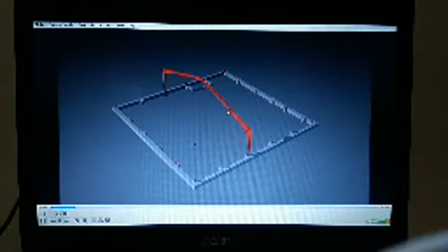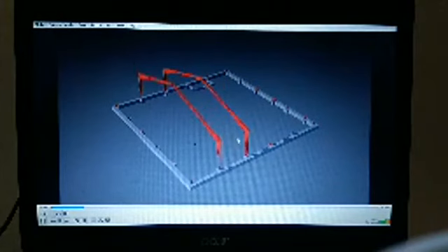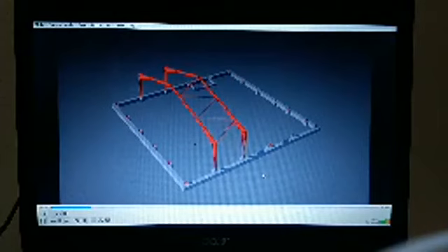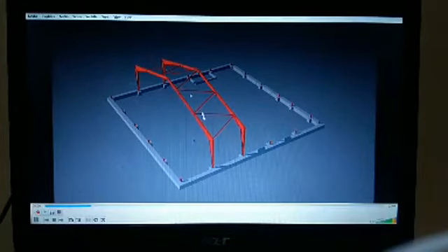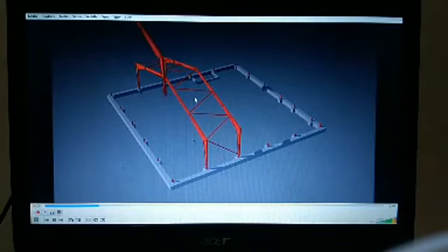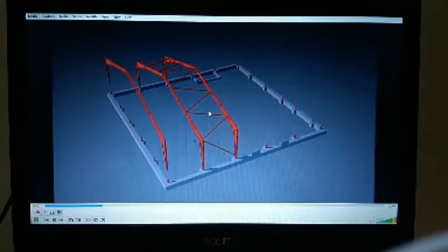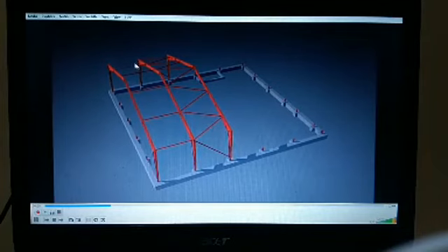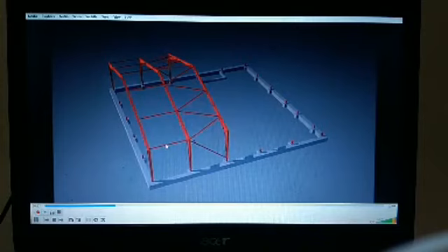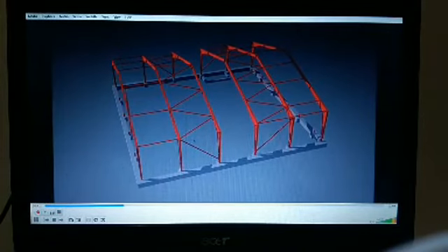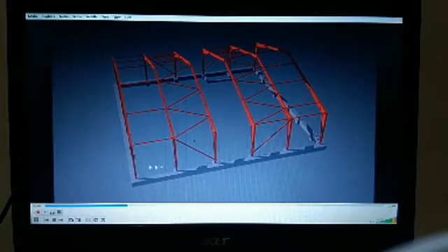Here the video you are observing is a PEB. It is an unbraced frame structure, which can also be called a portal frame structure. This is a bracing on the top of the roof truss, which we call a lateral bracing. These are the purlins, which are supporting the top chords of the roof trusses, and they are supposed to be designed as beams. And these are all columns.